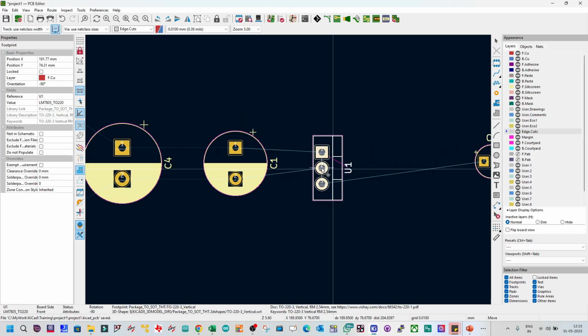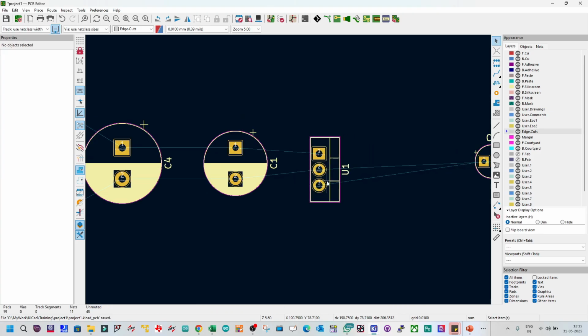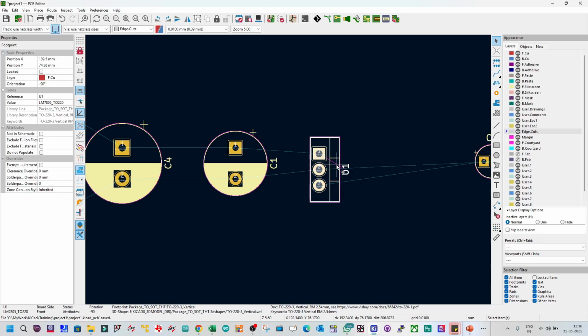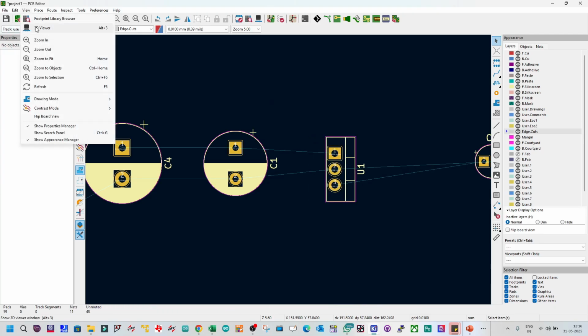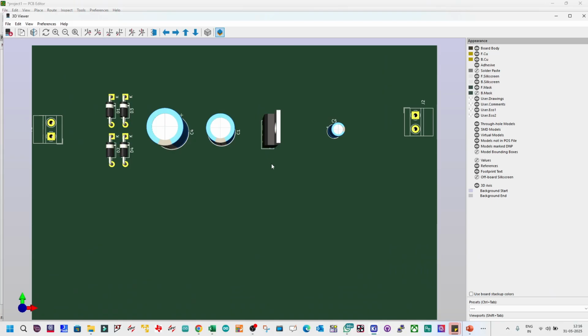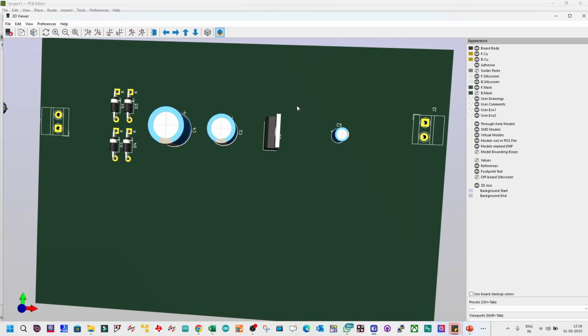See, there is a regulator. So now you see there is a problem. If you do a placement here, maybe I can switch to 3D view so that I can explain to you. Now if you put a heatsink here, this much area is needed. Am I right? So I have to make it free. If I put a capacitor just close by, in future there is no scope that I can put a heatsink here. But the idea is you must put the capacitor as close as the.